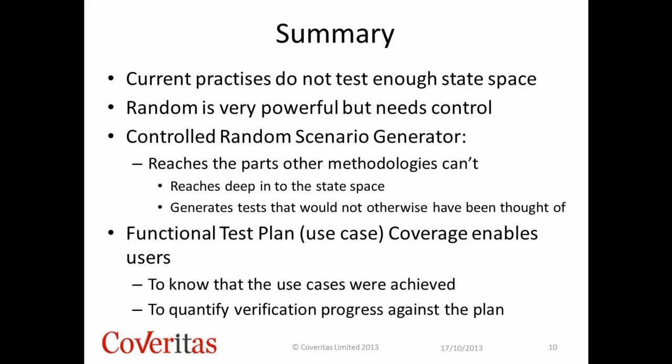We also use assertions an awful lot with customers. Within our libraries, we have some assertion capabilities, although there's nothing amazingly outstanding about assertions. But if you build assertions into the flow, into the methodology, then as you make each decision in the tree of what you want to do next, you can write or activate an assertion which says what sort of thing you expect. And that's a powerful methodology for doing checking.